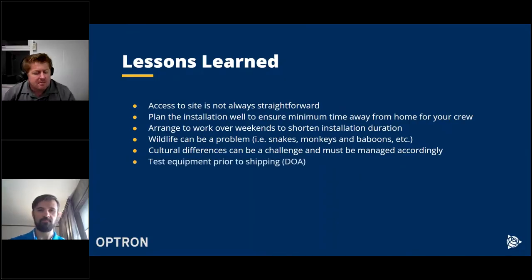And then test your equipment prior to shipping. You do get devices that get to your office and you install them, you switch it on, and the lights won't even come on. So then at least you're still in your workshop. You can replace it with a different unit, and you can send a working monitoring station to site instead of having to get to site and then find out that the devices are dead.